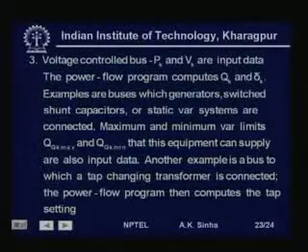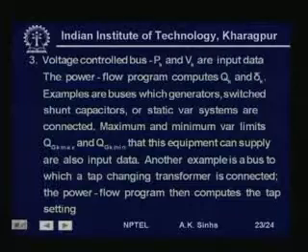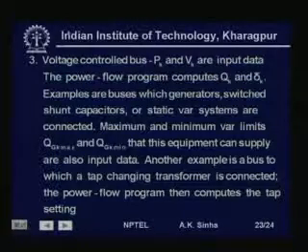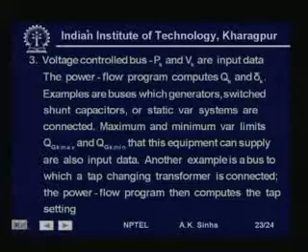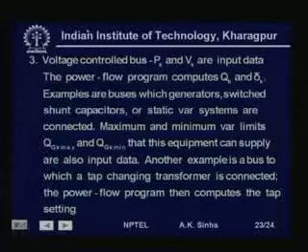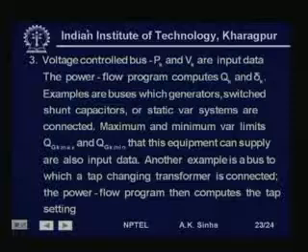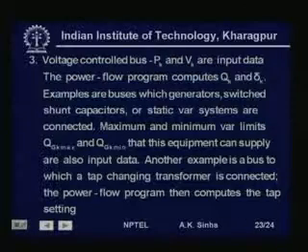We have a third type of bus bar which we call voltage control bus bars. These are generally bus bars where we have generation. At these bus bars, Pk and Vk are specified, that is the real power and the voltage magnitude are specified, and the solution of power flow will provide us the reactive power and the voltage phase angle.